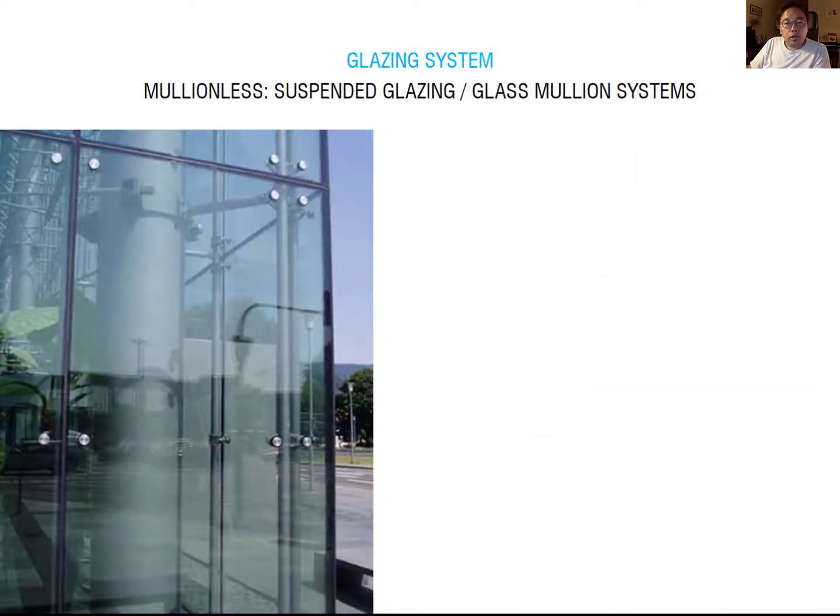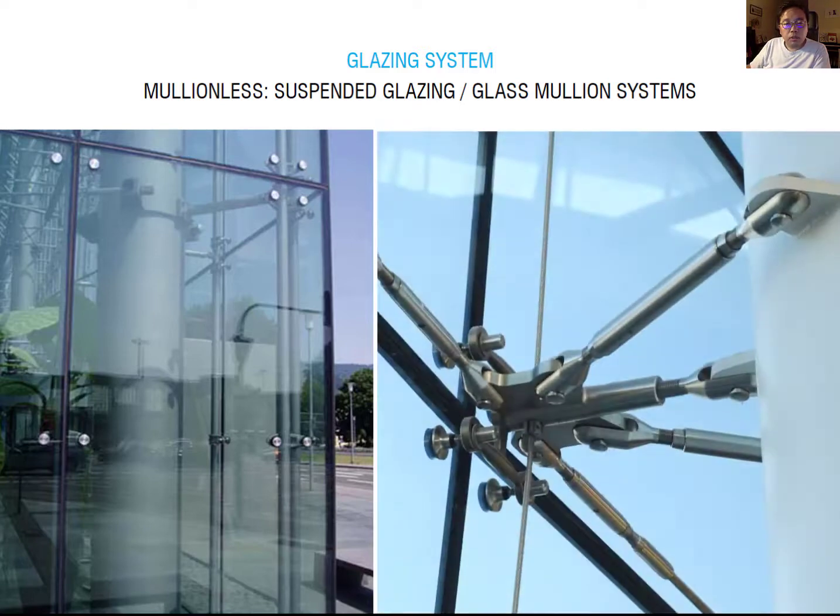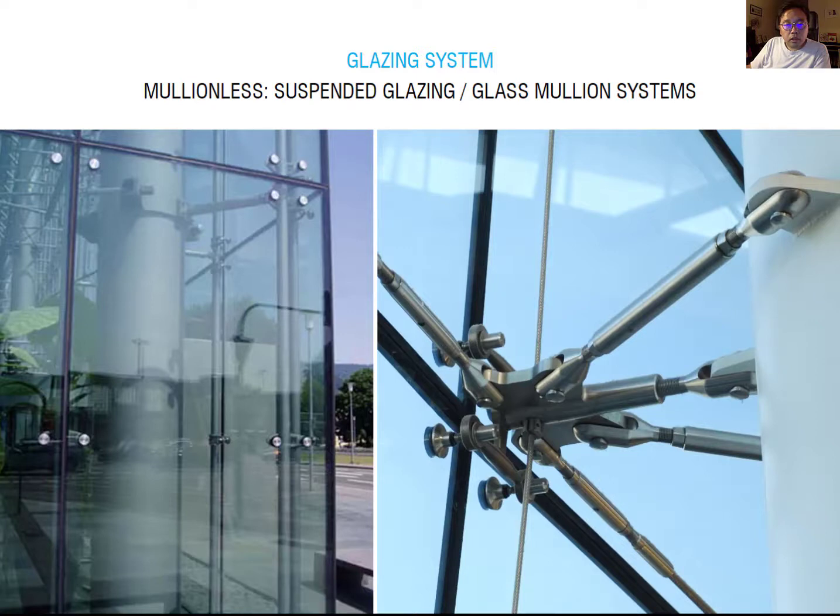So look at it in detail. You can see the cable and spider system tied to the column to support the panel. You can see the column, and then this adjusts the load, and then this is the main spider body, and it is supported by the cable and also mainly supported by the column here.